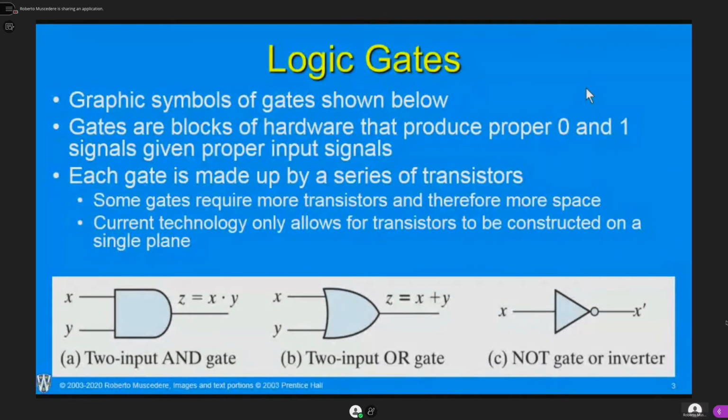We do have some play with this right now, though. I don't know if people have listened to the news about technology, but something we have been doing that's been reducing the size of memory chips is called wafer stacking. We can take individual chips and stack them on top of each other, and we basically solder them together. So there's a place where a signal can actually go through the chip, or we can provide a signal to the bottom of the chip and the top of the chip so we can stack them together. It's relatively new technology and it has its limitations, but it's definitely being used in memory chips to cut down on the amount of space needed.